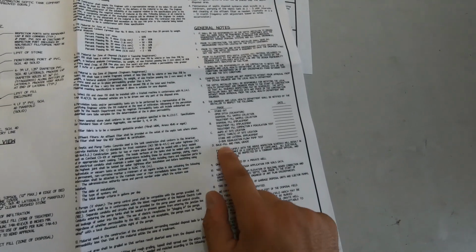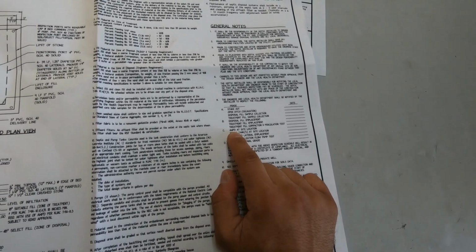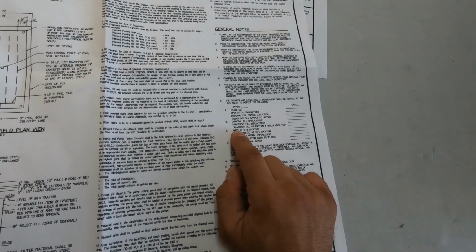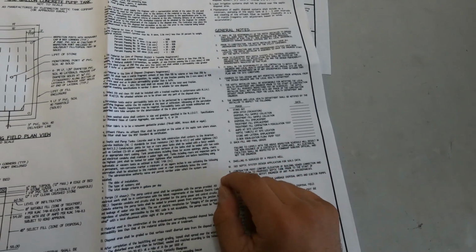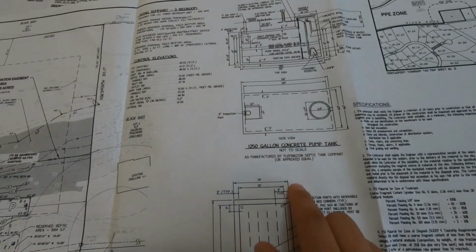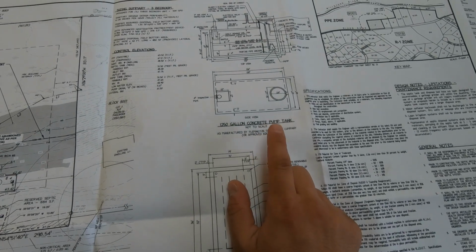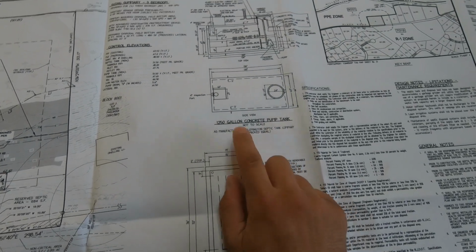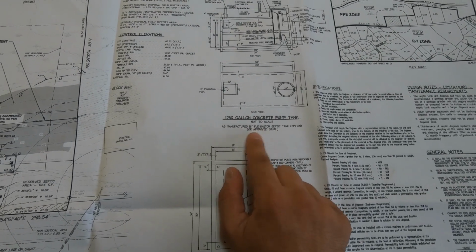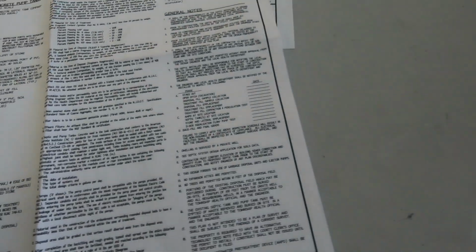Another thing that we're looking for, some of the things we inspect, we're inspecting the septic tank or the advanced wastewater treatment tank at the site location. So that's just verifying the size and material of the tank. Same thing with the pump tank, by the way, just verifying the size and material. And you can see that we use a lot of Flemington Septic Tank Company tanks or Flemington precast tanks or an approved equal. So if it's not one of those, just make sure it was approved by the design engineer.